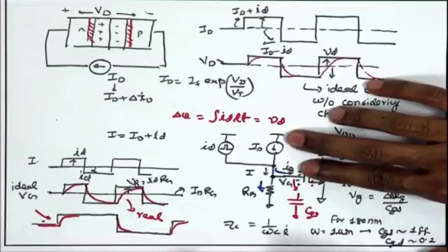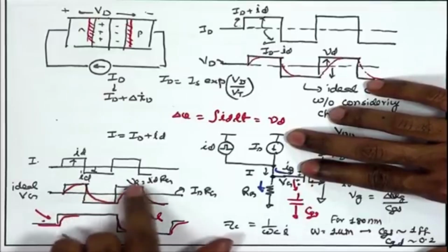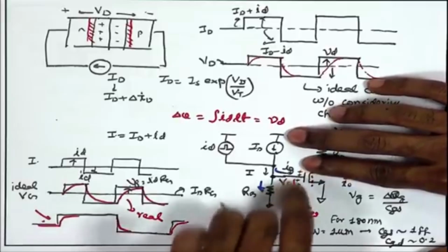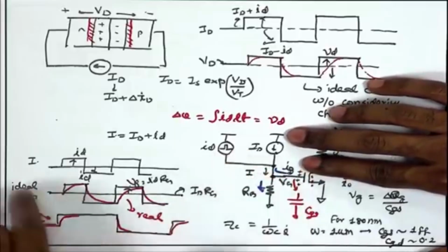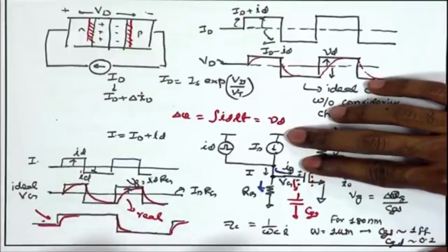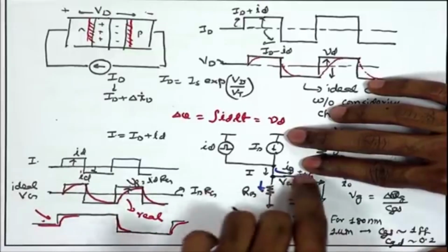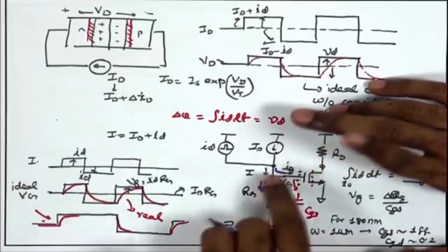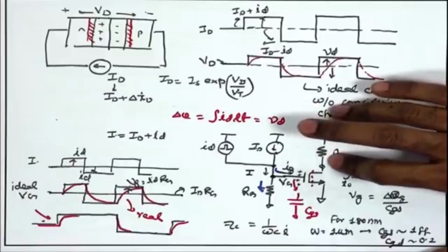voltage increase. So, your waveform is going to be more sluggish, and as a result your circuit response is going to be slower, because you are trying to increase the gate voltage instantaneously by increasing the gate current, but this capacitance, because of the charge storage mechanism, is slowing down your behavior. Same thing will happen on the drain side as well.